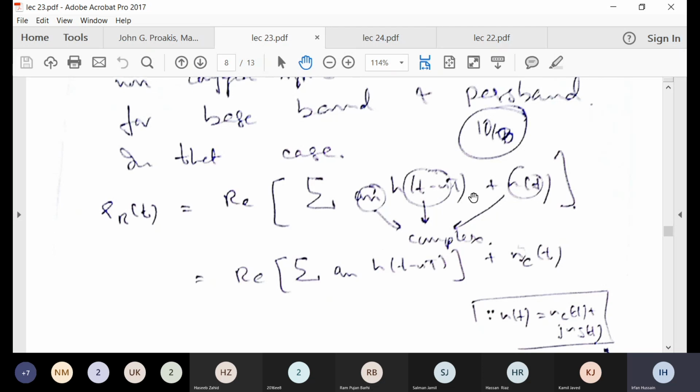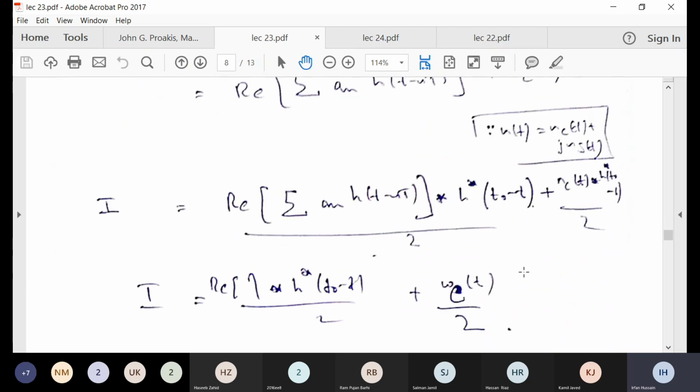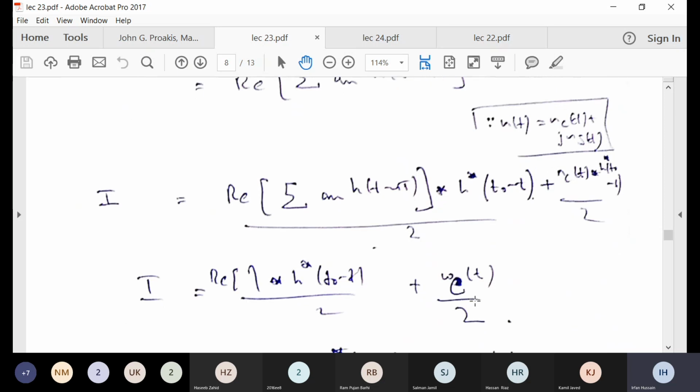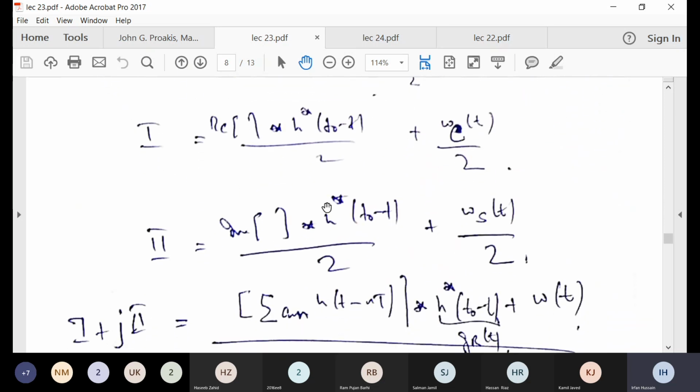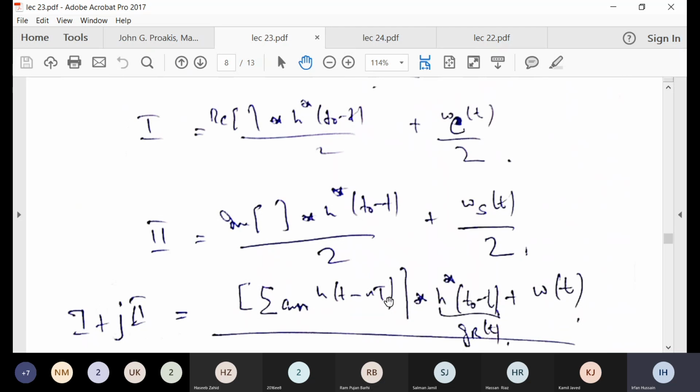So we know r_R(t) will be just the real part that comes out with the cosine. Then that will be convolved with h, and noise will also be convolved with the complex conjugate of h. The imaginary part will come out of the sine, the imaginary part of the whole. Again, it will be convolved here. And then if you sum 1 and 2, you can see that your total complex sequence, having complex symbols and complex coefficients, is being convolved with the conjugate of that complex coefficient.